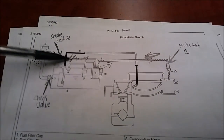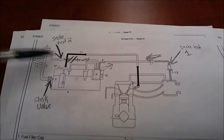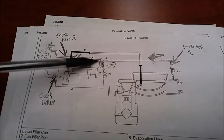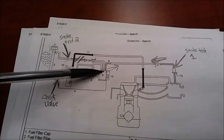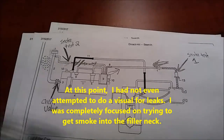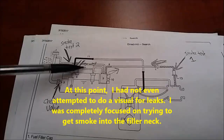For our second test location, we tested right here. We disconnected this hose going to the filler neck, and we pumped smoke in this direction back towards the canister. I also think that potentially that may have worked. We may have been able to pressurize the canister from that location. Again, I changed directions off of that because I still couldn't get smoke out of this filler neck. So, I was starting to get a little frustrated by this point, to be honest, guys.